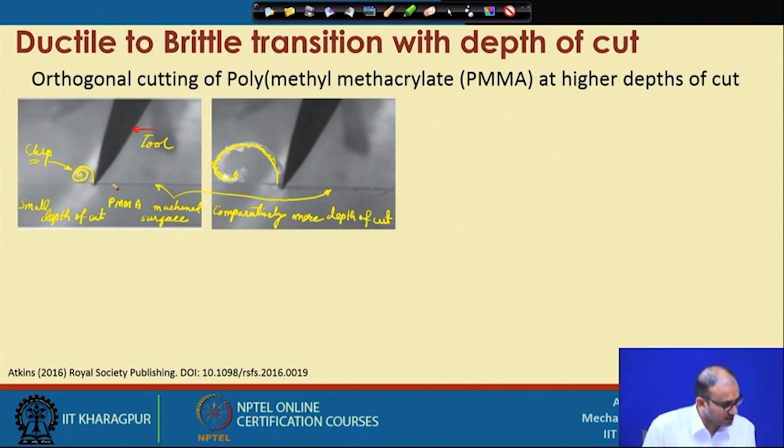Now, you can see here it is a very clear surface. That means no material is left uncut, or no fracture happens, or no cracks, nothing is here. But if you see this particular location, you can find a very clear layer here which is deformed. So, this is the deformed layer, due to more depth of cut. Okay. So, let us continue further.